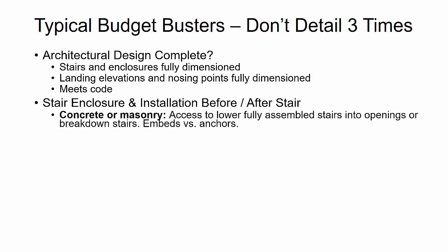So what I mean there is if we look at the concrete or a masonry system that's going to be enclosing the stair, then that oftentimes will actually be put up before the stair is installed. Because the stair is going to frame into the cast in place concrete where there might be embeds, or expansion anchored or wedge anchored to a masonry wall, basically you need to have dimensions fully clarified, and you're going to potentially need to detail the stair broken down, and it has to be field fabricated because of access, since the enclosure is mostly already out there on the job site.